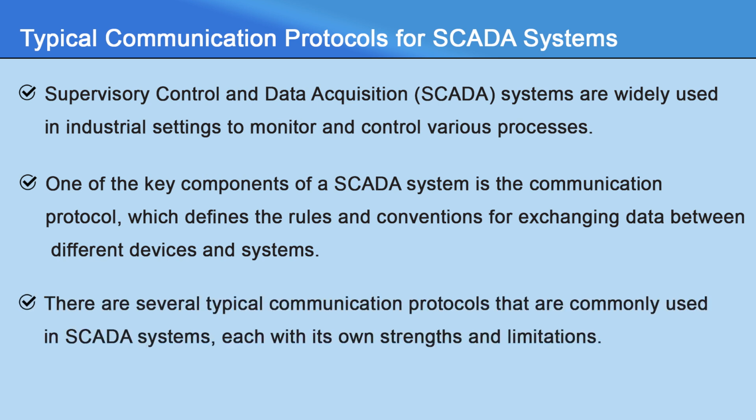Like the PLC, there are several typical communication protocols commonly used in SCADA, each having its own strengths and limitations. One of the most widely used communication protocols in a SCADA system is Modbus, which is an open standard protocol that is simple and easy to implement. It is often used for connecting remote terminal units, RTUs, and other field devices to the SCADA system.